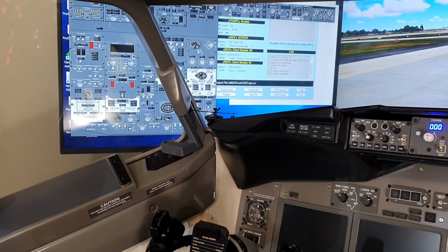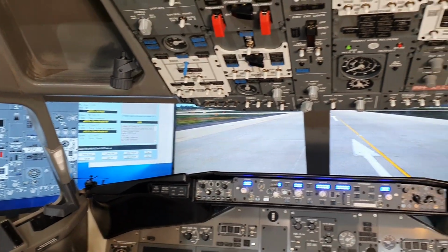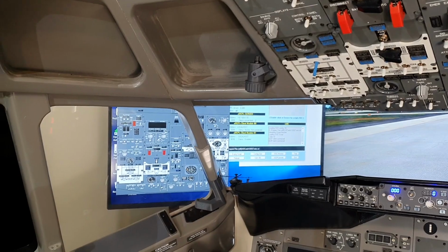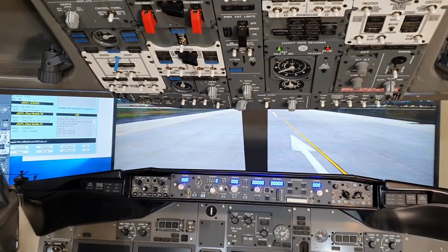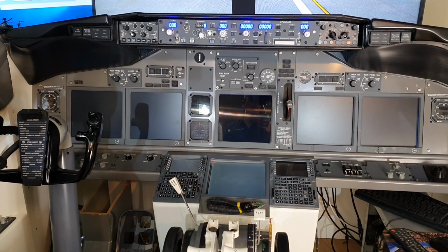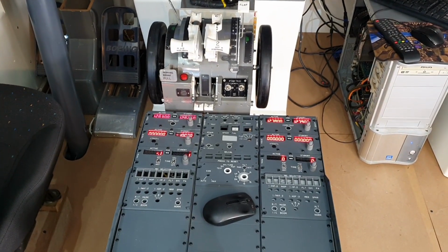That means when I come to do the switch check on the upper overhead, we can make sure that when I push a switch, ProSim thinks it's getting the same command. Makes it really easy for fault diagnosis. And the first fault we can see is that we've got all our 7-segment displays showing even though the power is off.